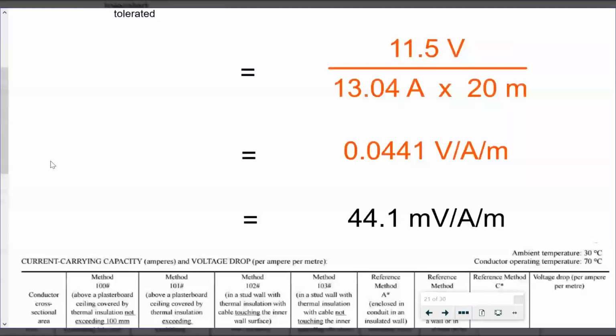However, when I carry out a cable size calculation, I look at the overload side of it first. I make sure I'm not going to burn the property down rather than making sure the piece of equipment works. So first thing I do is that overcurrent calculation, the overload calc, making sure that the cable's not going to have any or too many hot spots in it under overload conditions.